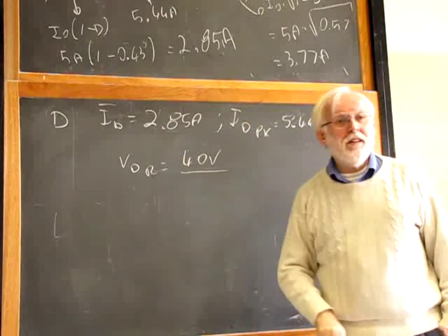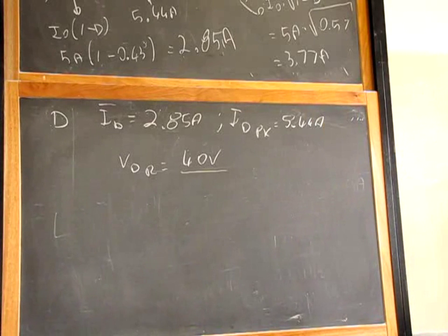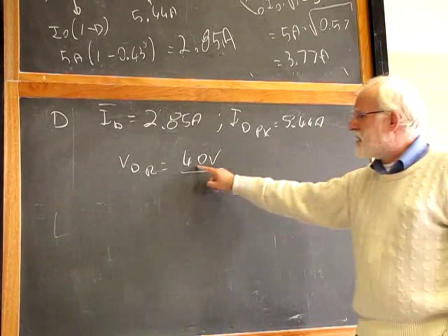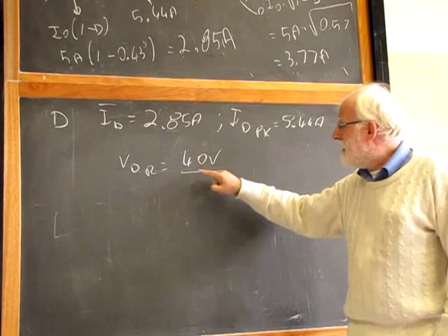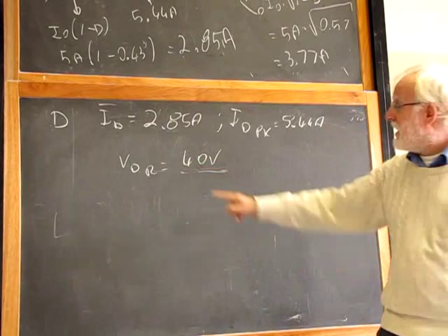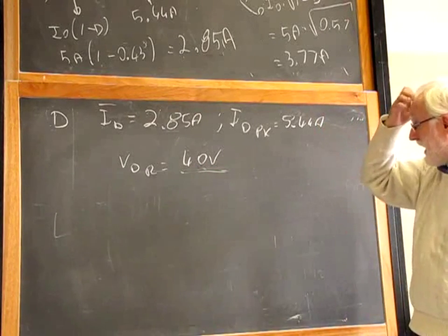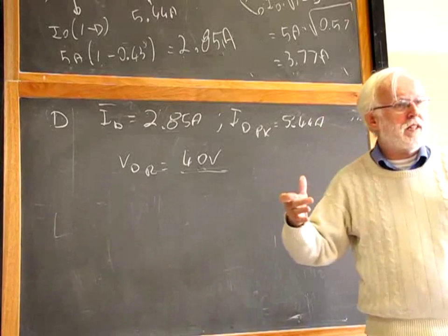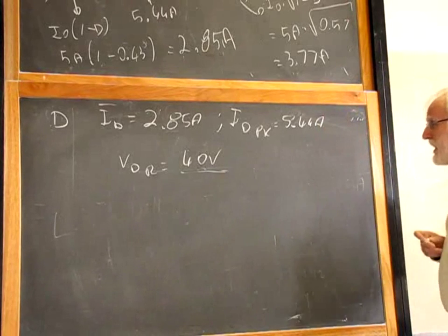This value is normalized, but it's not normalized with the standard resistance values, 10, 12, 15, etc. Those are, in some cases, normalized according to the E series for capacitors. In other cases, you have to go to the catalog. For Schottky diodes, by the way, 40 volts, we can use a Schottky diode. Schottky diodes means you can have 20, 30, 40, 50, 60, 80, 100 volts or so. More or less the resolution is different.